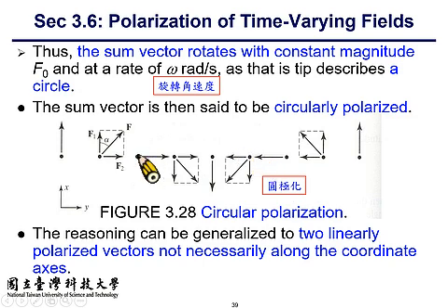Here we see a true linear polarization. If the two linearly polarized components have the same magnitude and differ by 90 degrees, and they are perpendicularly polarized, then the addition of the two can form a circularly polarized wave. That's an example of a composition of circular polarization, which means the direction of the total E field will trace a circular path.